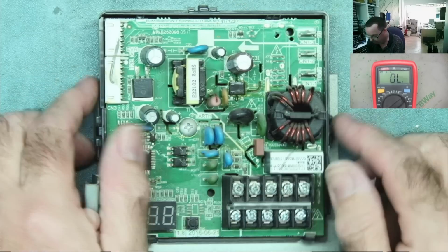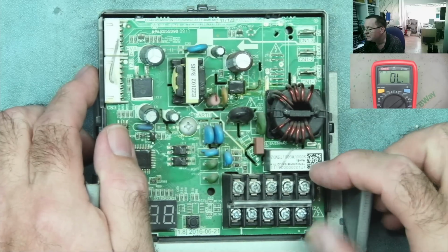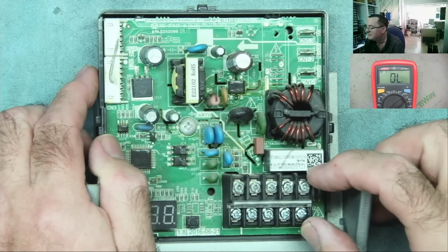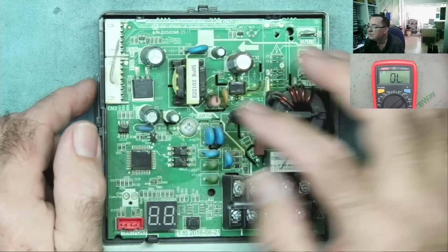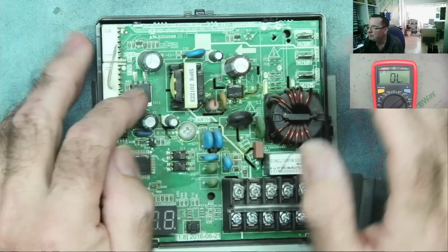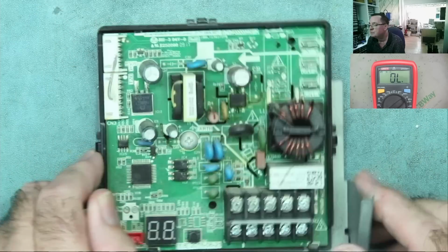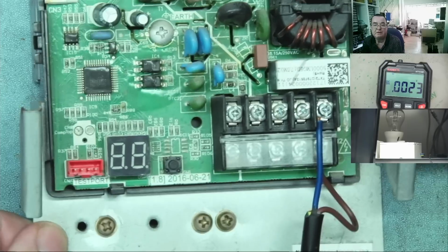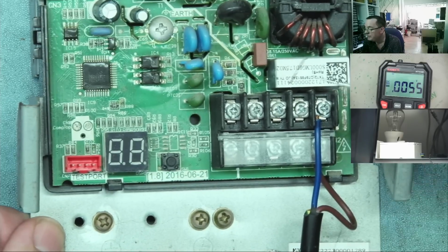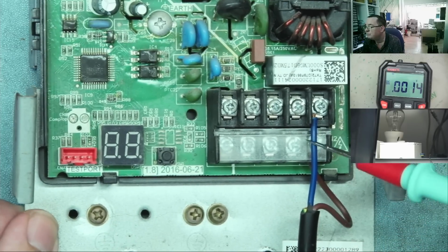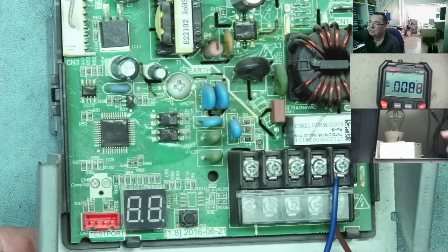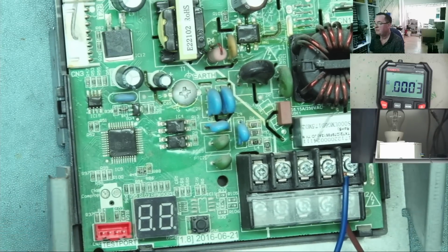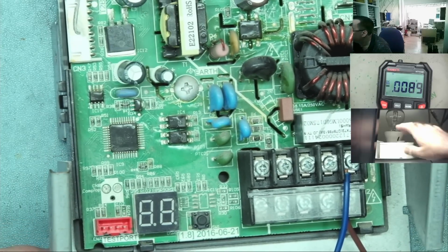Nothing was going bang on this, so I think what we'll do is we'll attach the power. We could attach it here or here, to be quite honest, and let's see if we have any output from this power supply. This could be the first point of failure, so let's have a look. Okay, so I've attached the power as per the diagram, so live and neutral. I've attached the current limiting light bulb over there, but this probably won't do very much.